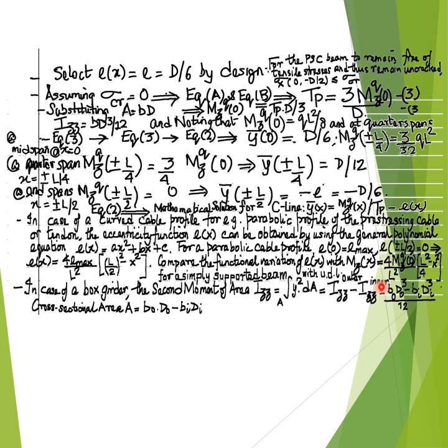along the x-axis, simply because the function representing the cable profile, that is the profile of the pre-stressing cable or pre-stressing tendon along the x-axis, denoted as e with the argument x, can also be represented by an equation for a parabola, that is the functional variation of the eccentricity e with the argument x